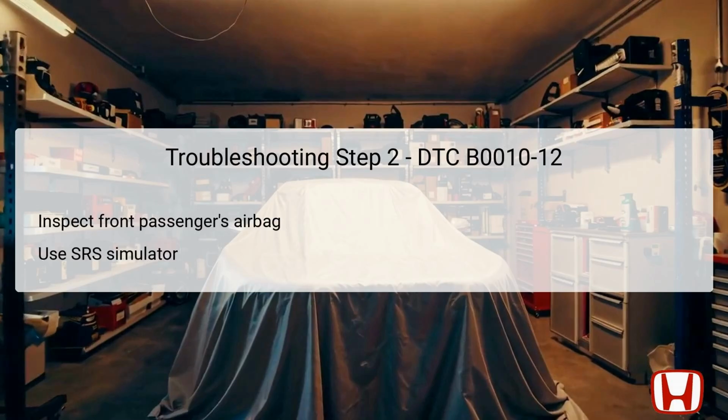Next, you will focus on inspecting the front passenger's airbag itself. Start by disconnecting the front passenger's airbag inflator connector, which connects to the dashboard wire harness. By using the SRS simulator lead J coupled with an SRS inflator simulator, you can test the airbag inflator. Connect the simulator's terminals to the airbag connector to emulate its functionality.